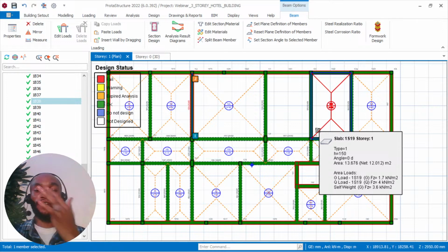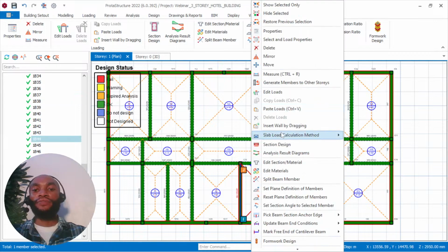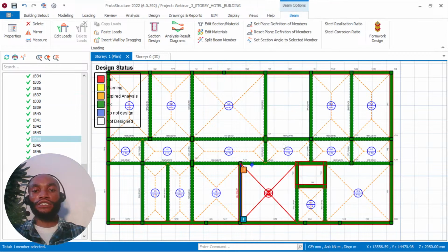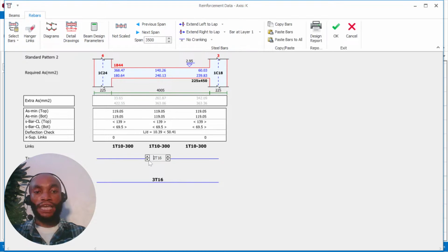Okay, that's fine. So with this again, I'll come here and check this also, then check the design for that and see if I can reduce cost on this beam. If I reduce this to 2 here, no, the area of steel here is very small. You can see it's showing 33.65, which is very low. So I'll increase it back to 3.